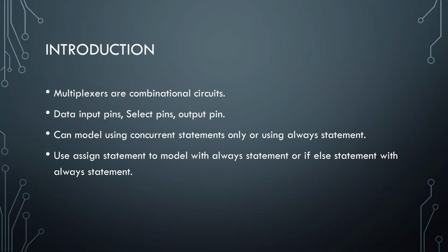We all know that multiplexers are combinational circuits, and as we stated before, for a multiplexer there will be 2 raised to n data input pins, n select pins, and one single output pin. We can model this by using the concurrent statement only or using the always statement.